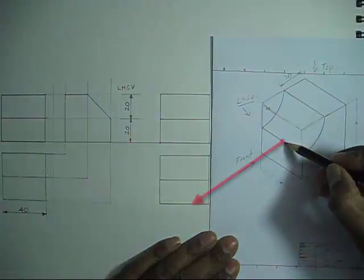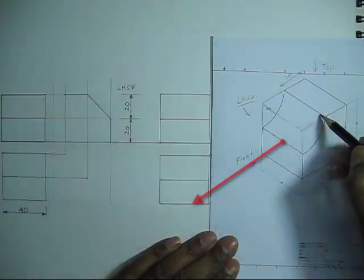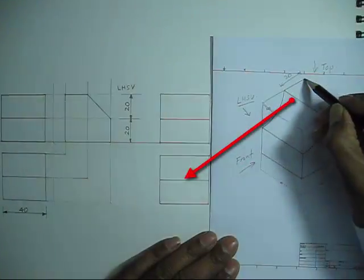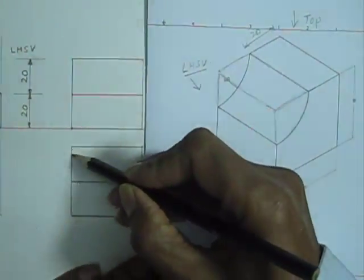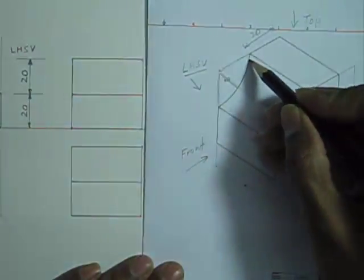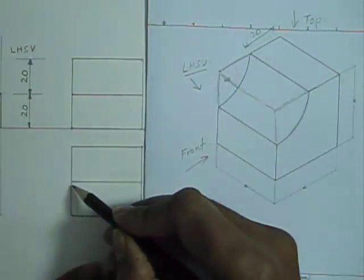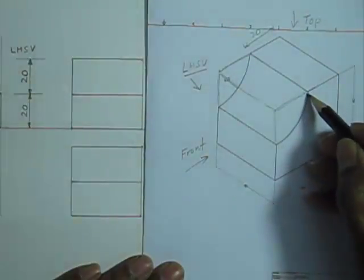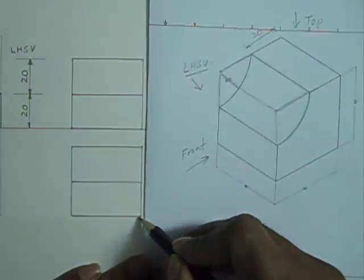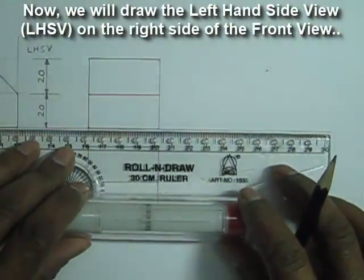This corresponds to the new edge which has been projected, and this is the new edge in the middle. And the curved part is projected as a straight line of length 20 mm. So the top view is ready.